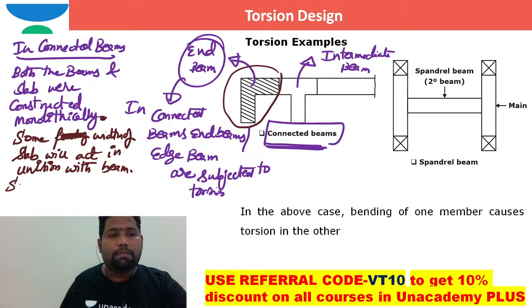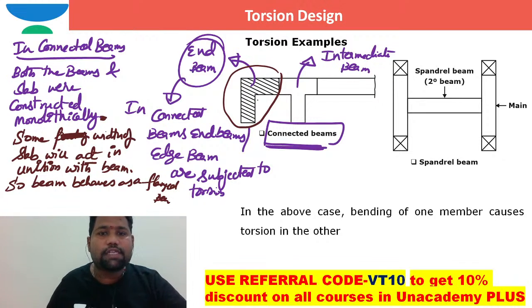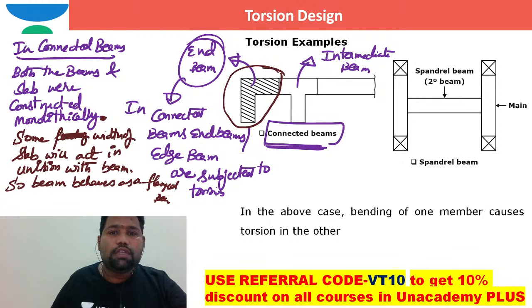So the beam behaves as a flanged beam. So that's the reason why I had shown this end beam is not a rectangle. I had shown this end beam as an L beam here, because some width of the slab will act in unison with this rectangular beam. So the behavior of the beam is just like that of an L beam.